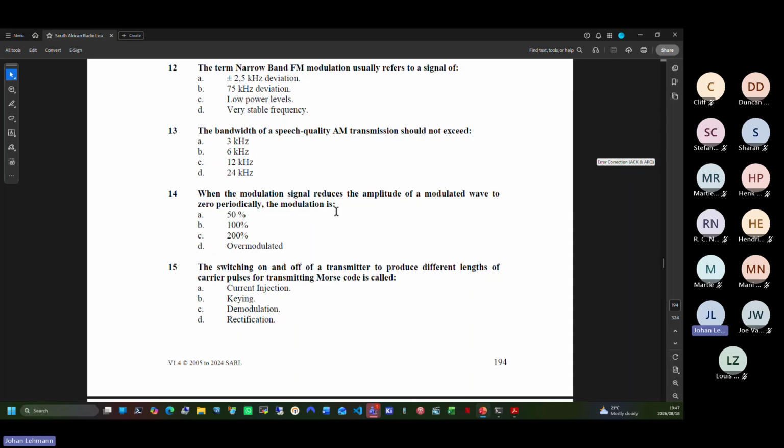Remember, if you go back to those little graphs that I showed you on amplitude, I said if we get to 100% modulation, there's a little bit of a flat line in between the audio frequencies. So if it's over 100%, then it'll be a massive flat line. Yes.